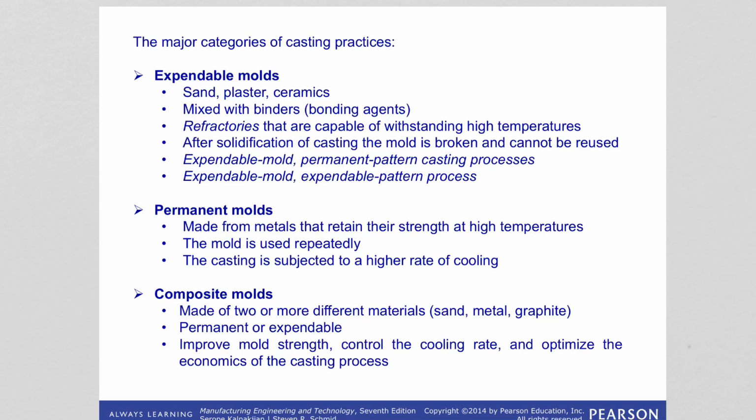Okay. Because these molds are better conductors compared to molds made out of sand, of course you can understand they are better conductors, right? One is a ceramic, one is a metal, and metals conduct heat much more efficiently, and we learned that the conduction of heat from the molten metal affects their structure.